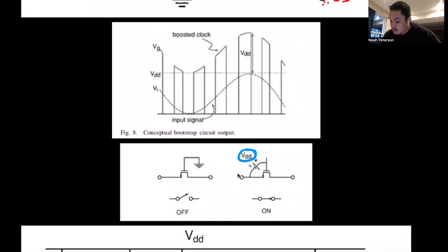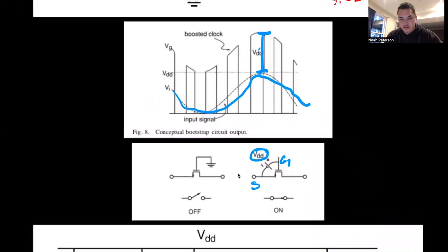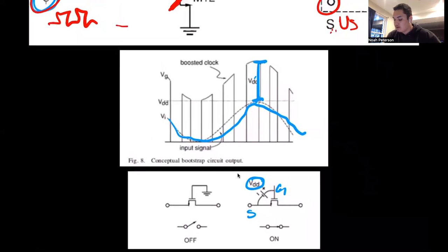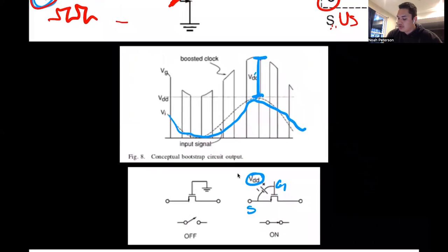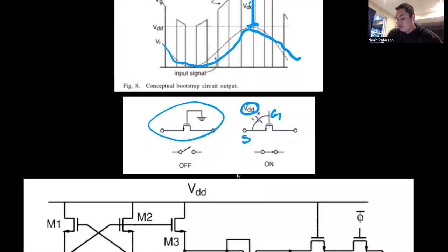And so what this circuit fundamentally does is just give us a constant voltage source across G and S. And that allows us a low distortion frequency and constant VDD to adequately track the input signal. And that just yields a low distortion signal and low power as well, versus just your sampling transistor, which will distort the frequency quite a bit.